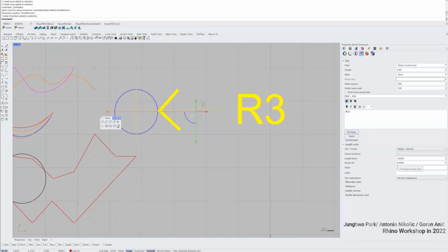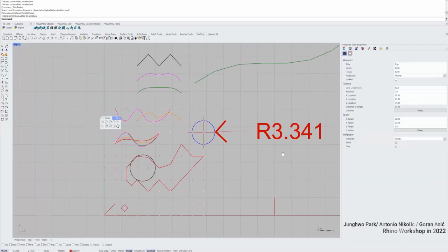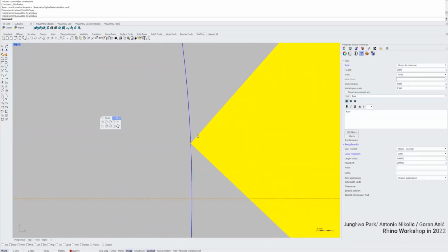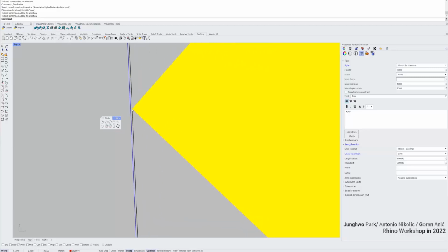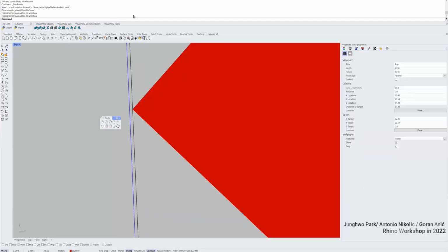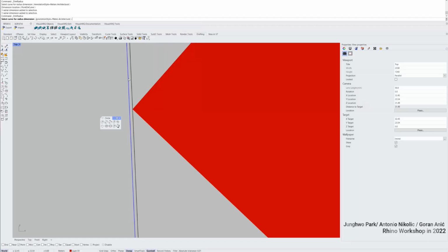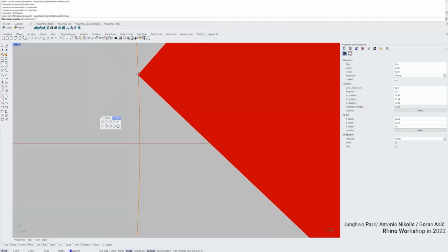Length unit is meter. Precision is decimal, meter decimal. Let's make it a little bit higher. So that's the radius of the circle we draw, which is the black one. And I'm going to command the exact same one. If you want to go command history, you can right-click on the commands, and I can do radial dimension. And this time I will choose the blue one.